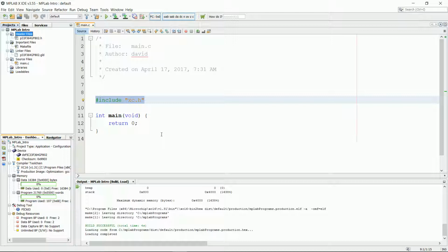However, regardless of what peripheral we use, we still have to set hardware configuration bits. And that is something that is done in code in C language, but our compiler can actually write the code for us. So that's what we're going to do rather than us learning all the details of the various configuration fields.